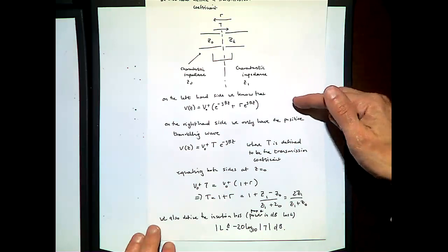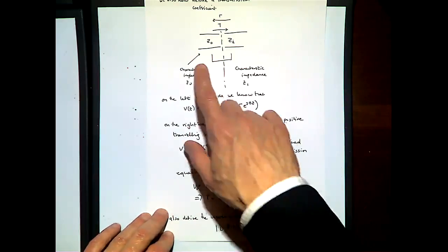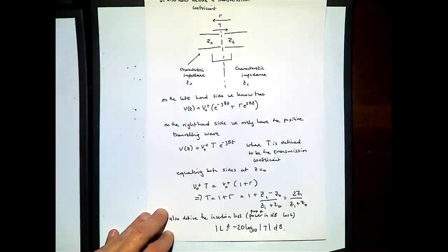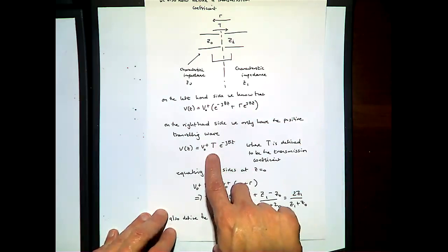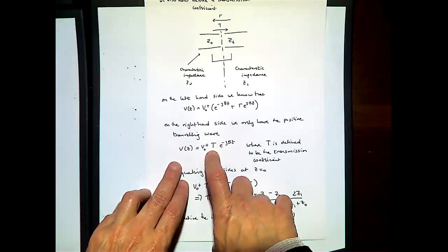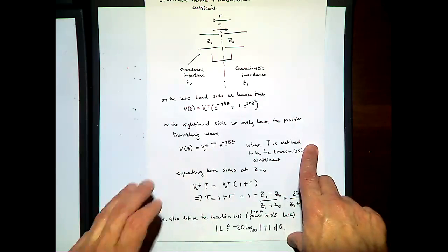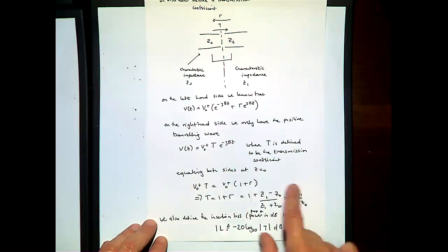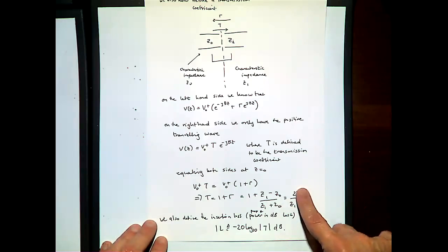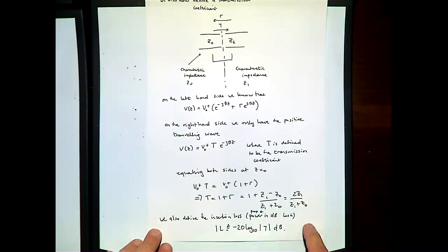Okay, so if we go through the calculations, what we can see is that if we've got an arbitrary interface between the characteristic impedance and the load, we've been talking about the reflection coefficient, but of course we can work out the component of power that's actually absorbed into that interface, and we define that to be the transmission coefficient. You can go through and convince yourself of the relationship, and how to derive that transmission coefficient. And importantly, what you've got is this concept of insertion loss, right? We've talked about reflection loss.